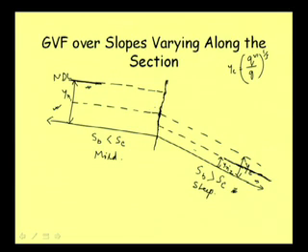So, ultimately what will happen, we know that this depth is critical depth, and as this flow will be affected by this one, from here this is the controlling point. At this point when the flow is changing, this point will be critical depth. So, from here it is starting like this, because flow will have to change from subcritical to supercritical.